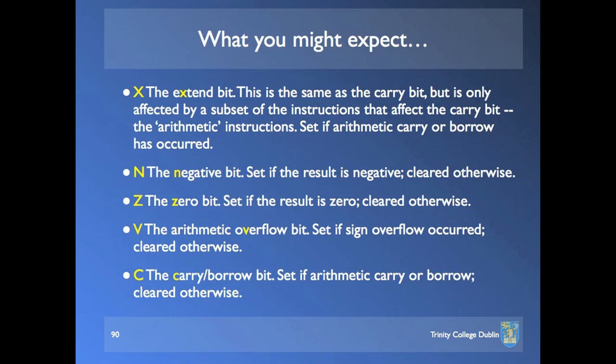Now I've put in this "cleared otherwise" everywhere because again, you need to be aware that the condition code register bits really are very ephemeral. They only really refer to the immediate past, they don't go back very far at all. The present and the immediate past.